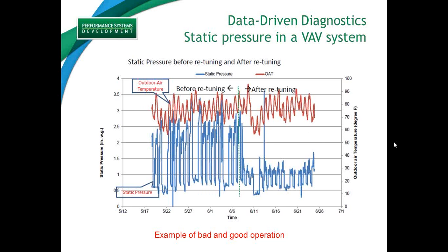We've done that before, where the project drags on forever because the control vendor doesn't really want to be that helpful. In other cases, it was very easy to get the data out. It was an Automated Logic system, pretty straightforward to understand. We had to learn it, but it didn't take very long. So I'd say, barring getting the data, analyzing the data in the eCAM tool and coming up with recommendations is probably on the order of less than a week, like several days, depending upon how good you are at the tool. So let's move on to an example.